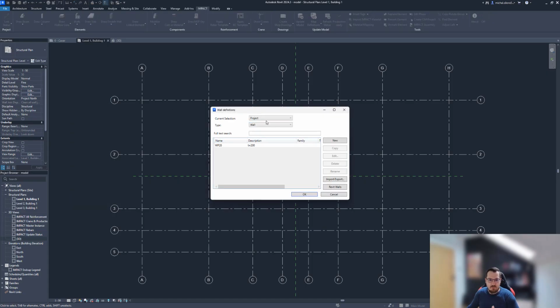You'll see that we have 3 levels in Impact. That's the project level, so all the types of elements that are defined inside just a project. There's the local level, so basically maybe a factory level, something just available in one particular factory, or a common level, so all the types of elements that are available in your company in general.